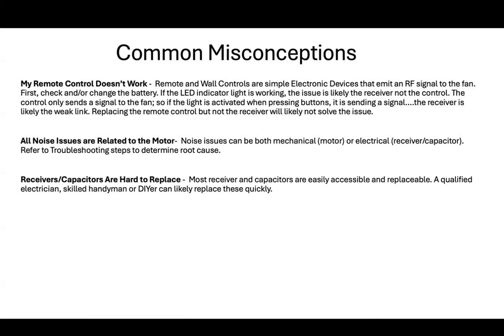All noise issues are related to the motor. Noise issues can be both mechanical, motor, or electrical, receiver and capacitor related. Refer to the troubleshooting steps to determine the root cause.